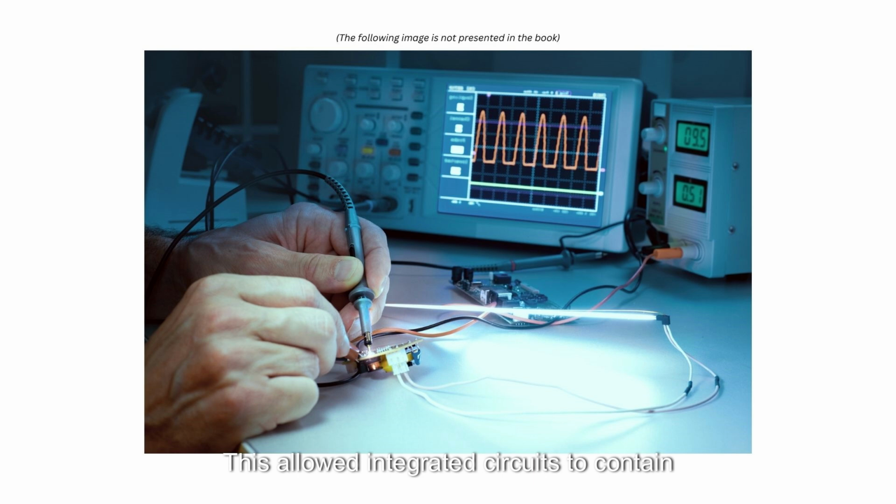This allowed integrated circuits to contain embedded memory, and the ability to put into a single chip what used to be done by dozens of discrete digital logic components. In addition, innovations in silicon allowed these chips to retain the information that was programmed into them by the user. This is known as non-volatile memory, meaning that the data in the memory of the chip is not lost when the power is removed. These chips are also capable of being reprogrammed electrically. In the past, erasing a non-volatile memory required chemicals or UV light. As a result, JTAG became synonymous with programming chips, rather than testing boards.